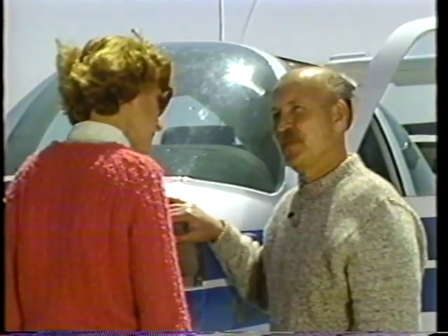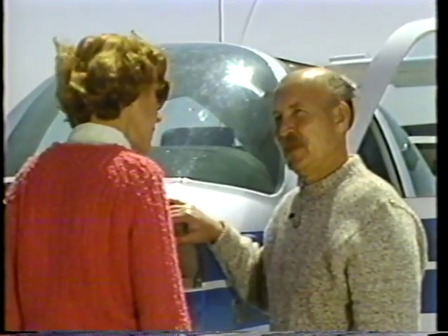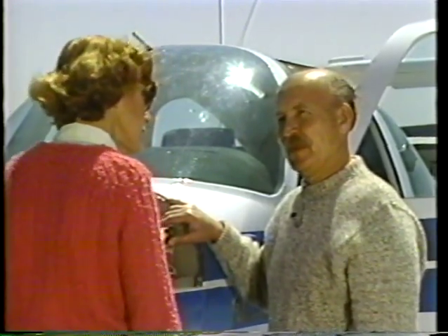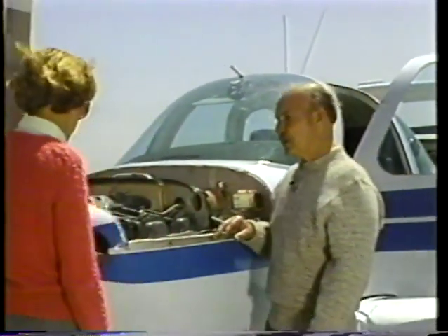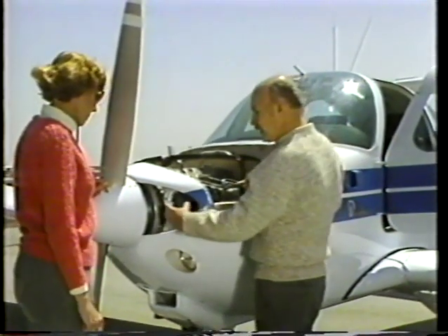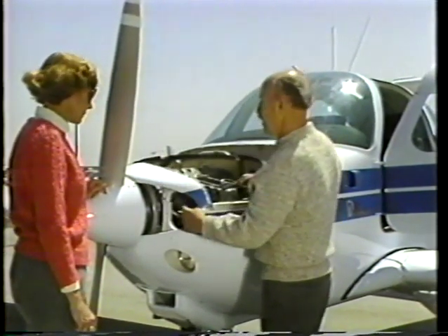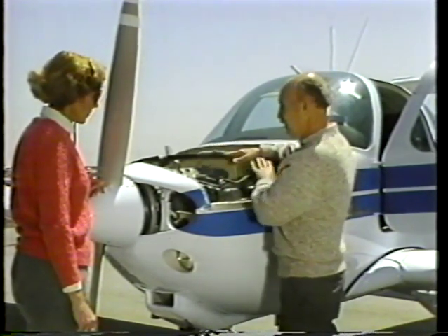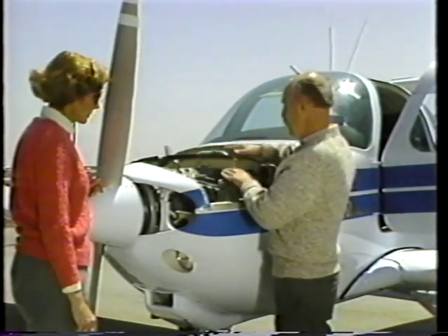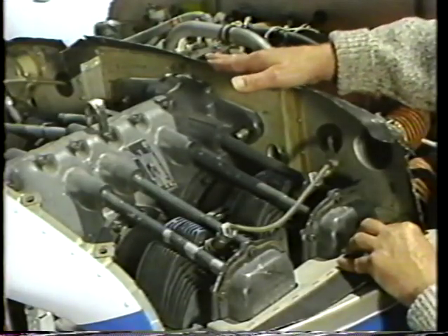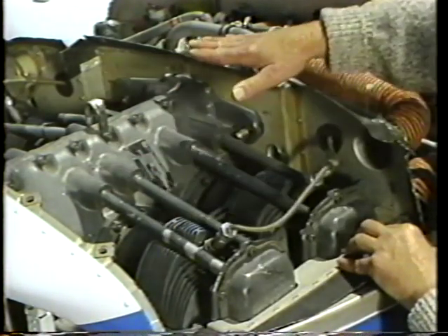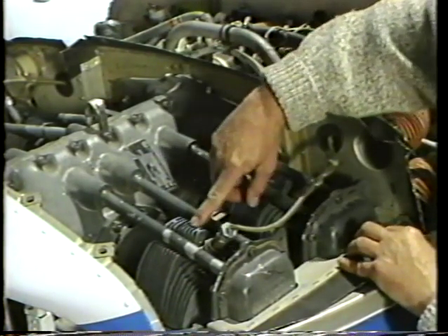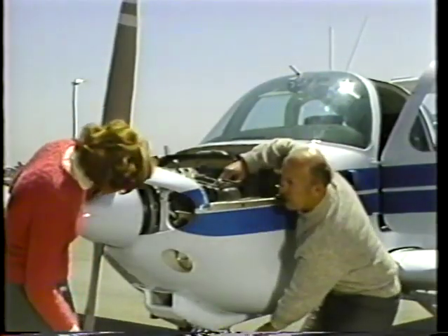Ken, with the tremendous heat energy that an aircraft engine develops, the cooling system is very important. Can you describe the Skipper's cooling system to us? Yes, Jeannie. The Skipper has an air-cooled engine, and the air enters through this port and the port on the other side. It enters into this chamber, and with the top and this baffling, it forms a high-pressure area here. The baffles keep the air from flowing out the back of this chamber. And the high-pressure air then is forced down through the cylinder fins. This carries away the heat, and it exits out the bottom.